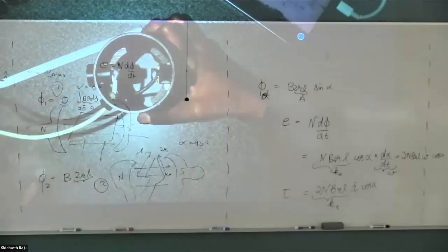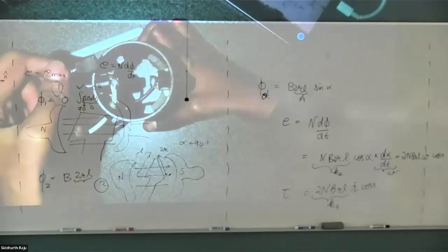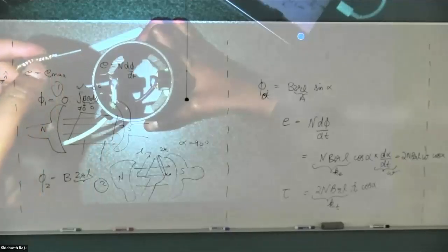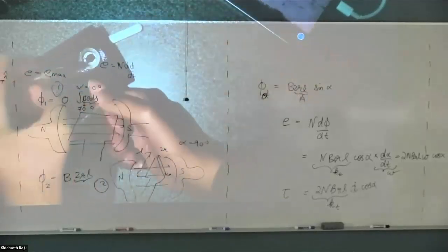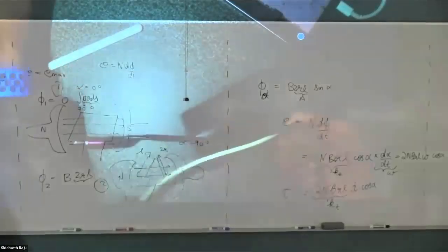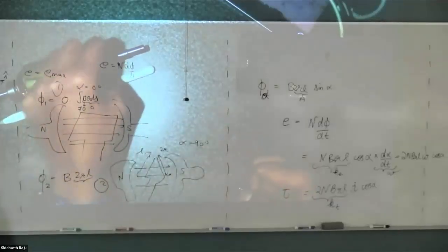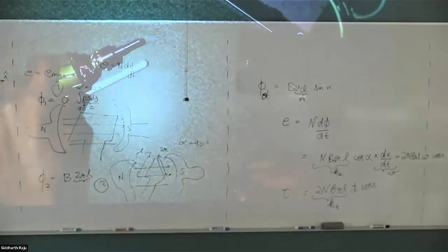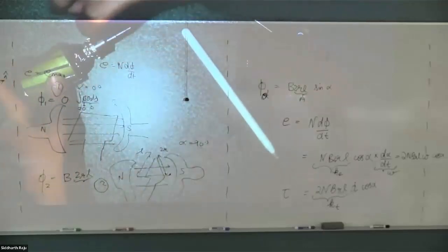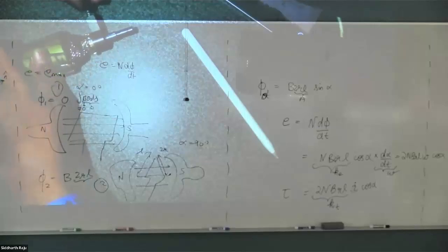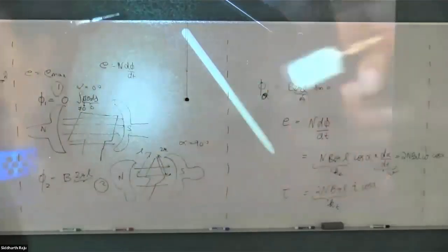this copper segment here, and I have this brush right here. This is just a pure graphite rod, and there is a spring attached to it. It comes through this slot on the top, goes inside, and makes contact with the commutator segment that I have on the rotor. As the rotor rotates, the brush is just going to make contact with the commutator segment as this rotor keeps rotating.